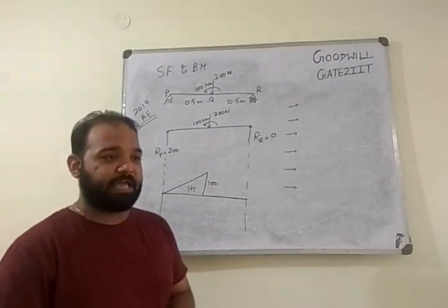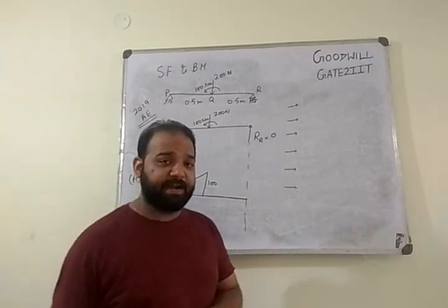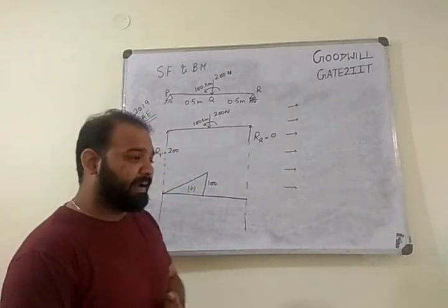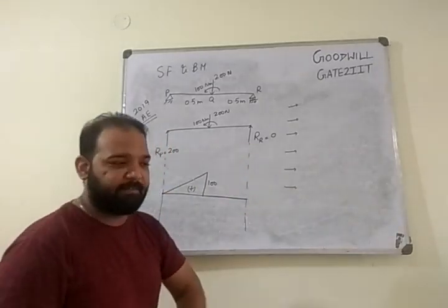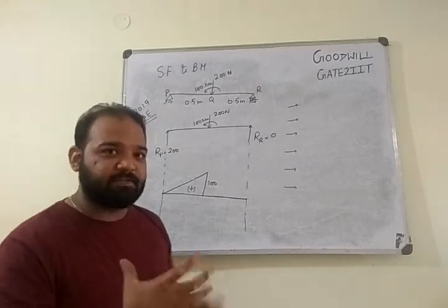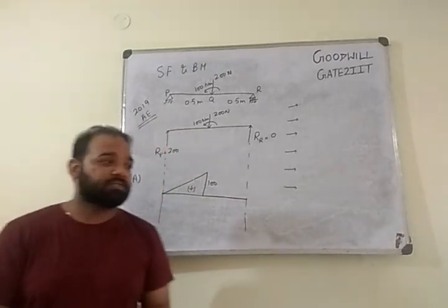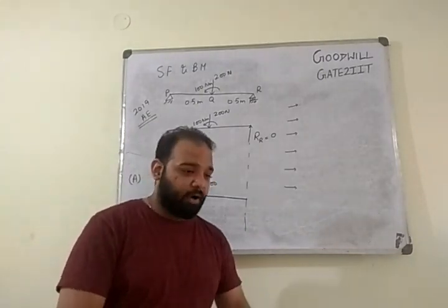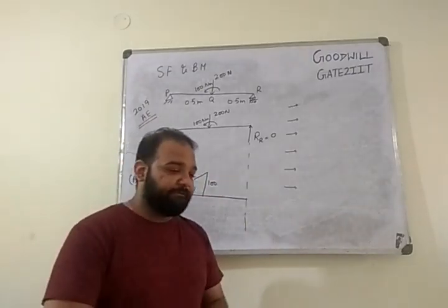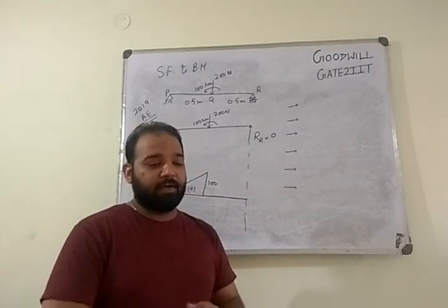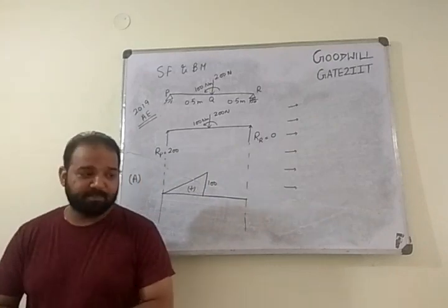Shear force follows the sign convention, which is known as right, upward, negative. You can change it towards the left-hand side accordingly. Then the bending moment diagram: we have seen these bending moments as positive, sometimes named sagging, that is a smiley face, positive. If your shear force diagram is 0, there is no force, then the corresponding bending moment diagram will be constant, referred to as pure bending. If your shear force is constant, your bending moment is linear. If your shear force is linear, your bending moment is parabolic.